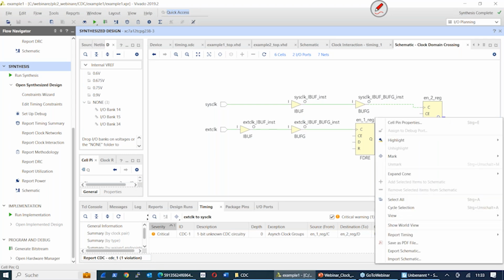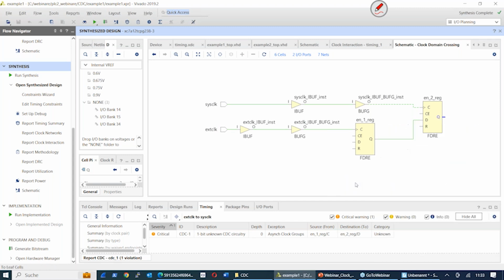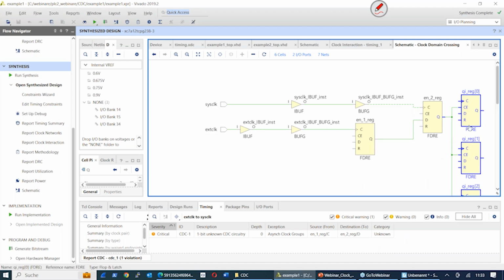I can also show you here. If I click on it and say expand, then you will expand to leaf. Okay, here we go. So then you see here that's a counter. So this means that's exactly here. That's the connection which is a problem. Okay, that's the clock. This clock, X clock, that's a problem. This will not work, and we'll get exactly this problem.